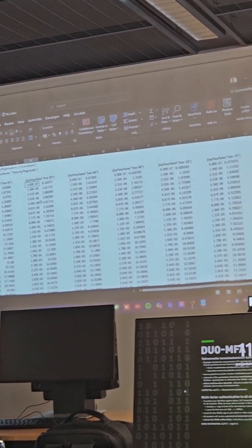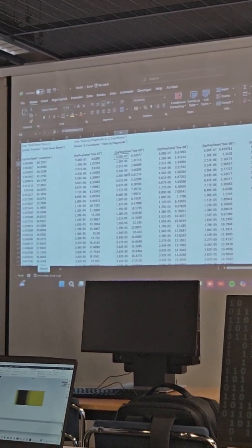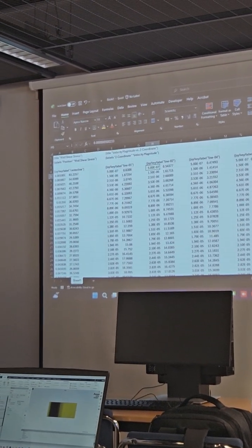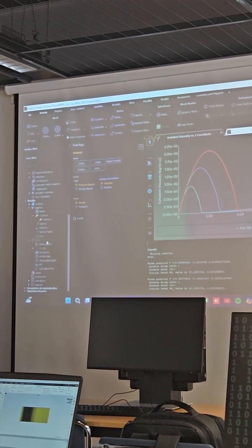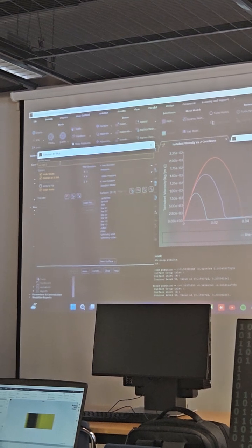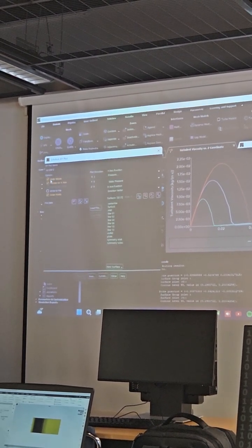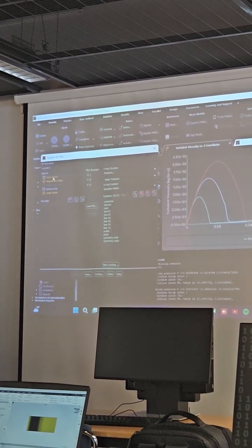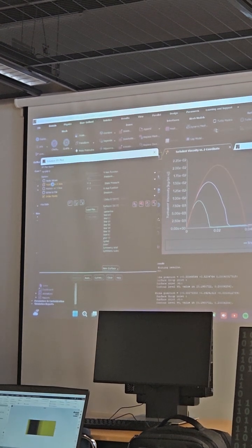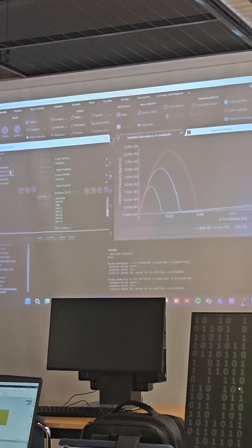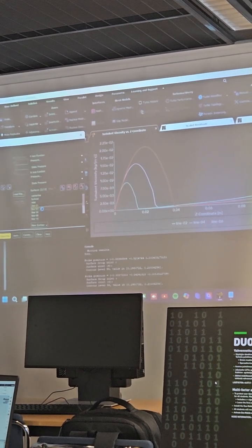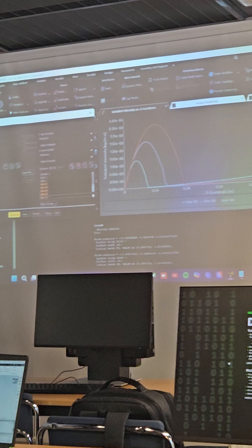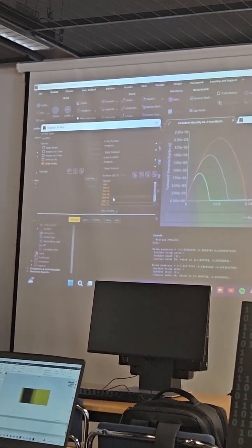Yes, please. I'm sorry, can you show once again how you've done to obtain this file? Yes. So in Fluent, you can open the XY plot. I was deselecting the node values. In this case, also the position on x-axis, I was deselecting this option. And if you have created these lines, you can just select the lines where you want to save your flow quantities.